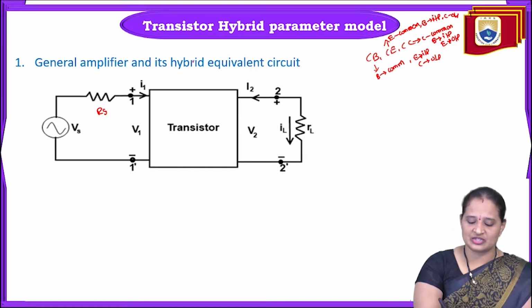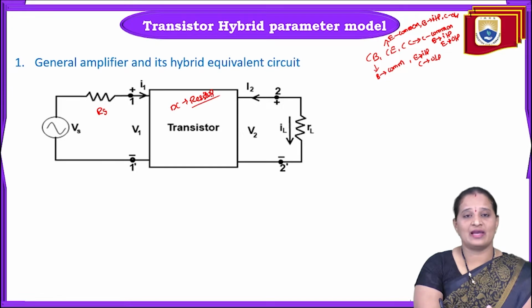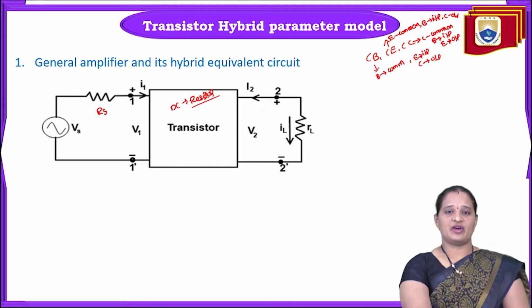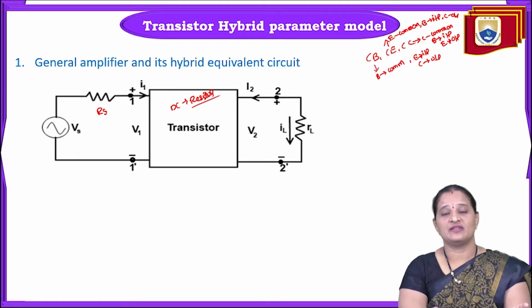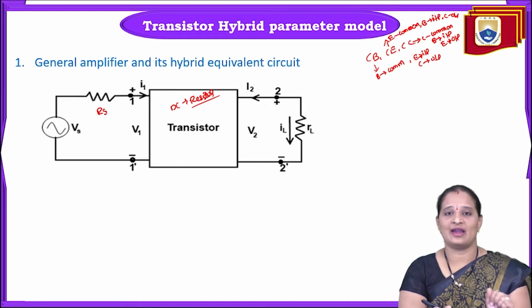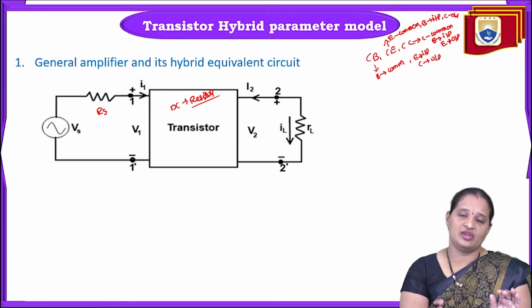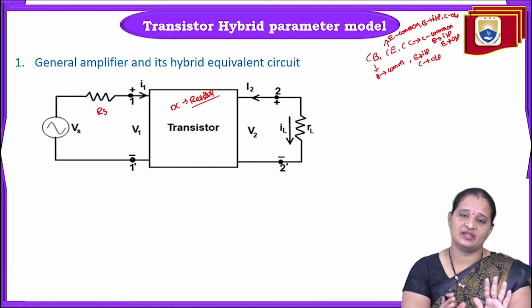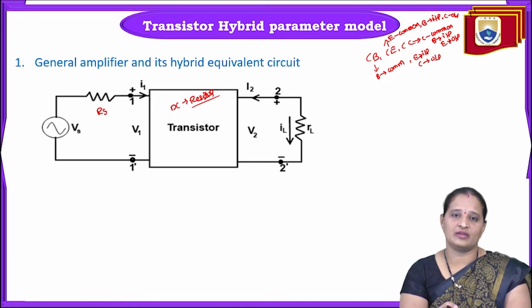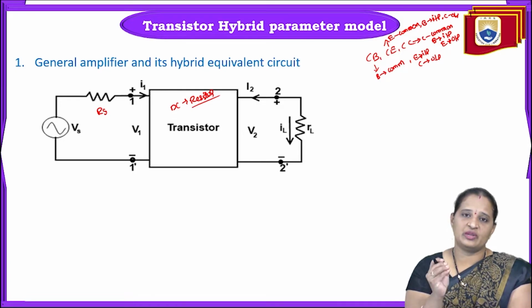So this is a transistor circuit where we can have DC sources and even resistors, such that the required biasing for the transistor is provided. As such, the transistor can operate in the active region. And we need to provide the biasing such that there is stability for the operating point. That means the operating point should be located in the middle of the load line.